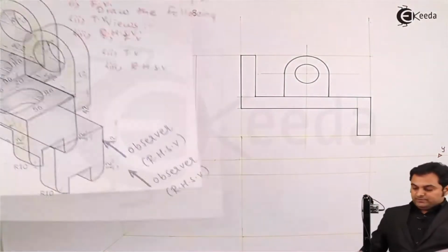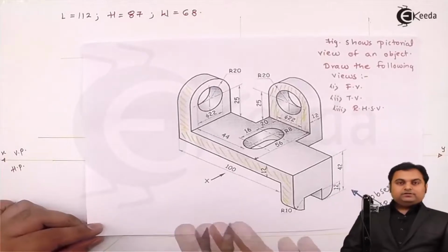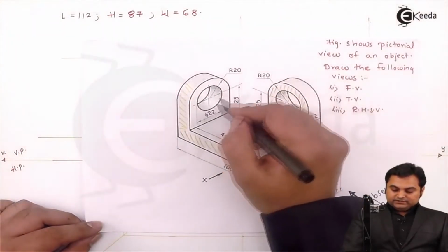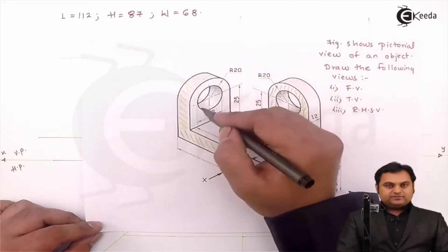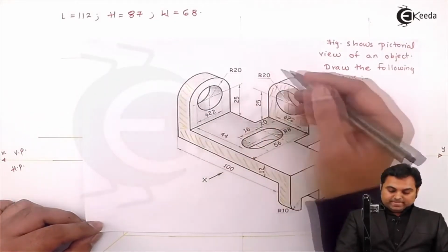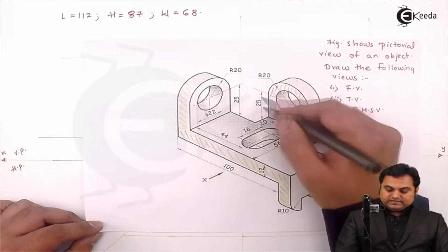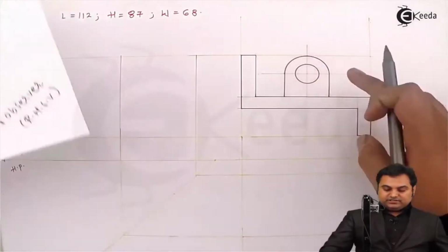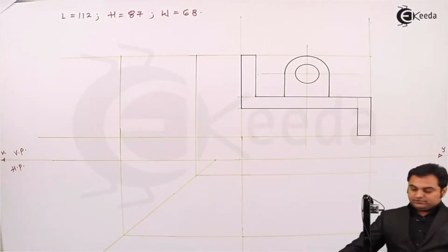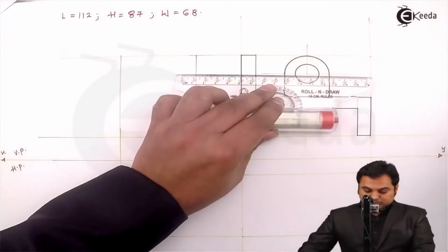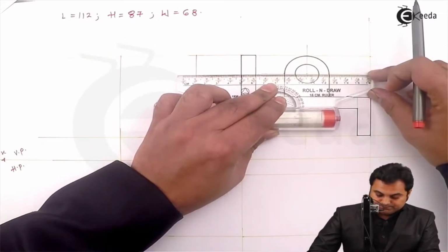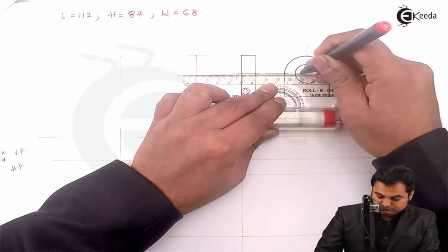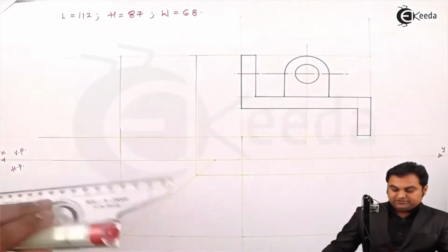So after this visible portion, now when we are looking from the front, in that case, this circle in the vertical plate is not visible. It is also having the same height, that is the same center and same radius as the semicircle I have drawn here. So first, I'll project the center line, having common centers.